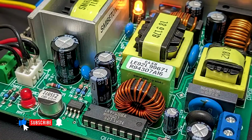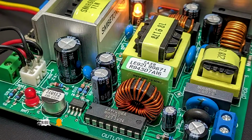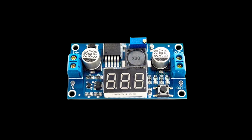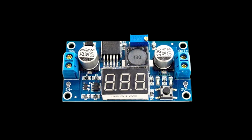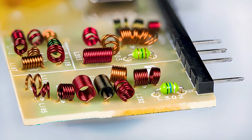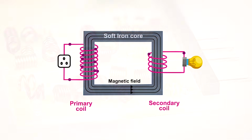Now think about real-world applications. In power supplies, inductors smooth out ripple currents. In DC to DC converters, they store and release energy rapidly to step voltage up or down efficiently. In radio circuits, they work with capacitors to create tuned resonant frequencies. In transformers, which are essentially coupled inductors, magnetic fields transfer energy between coils without direct electrical connection.